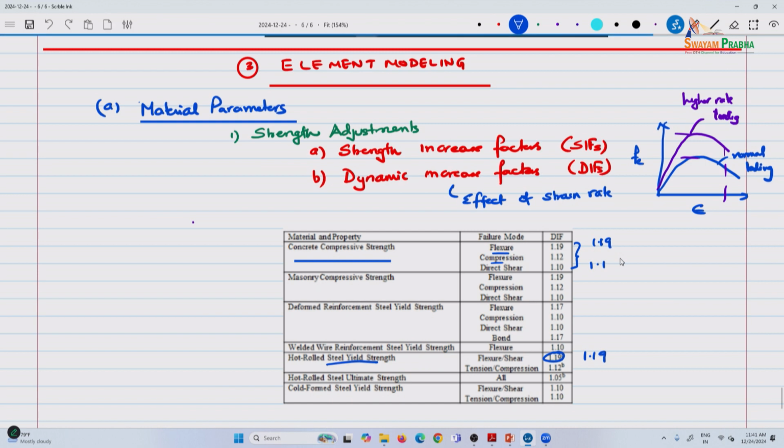Those are some of the other numbers, irrespective of the units that you use. What we were discussing during the break is that it is dependent on strain rate, and it is really hard to measure. Different strain rates are going to have different ratios, so if you ask what strain rate these are applicable for, it's really hard to answer that question.